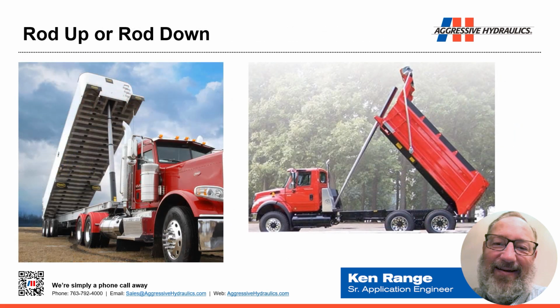You will notice that on some of these dump body arrangements, the case is positioned case down, rod up, or rod down and case up. That typically is a result of the real estate that's available on the vehicle. If you notice on the left, that trailer is basically a flatbed trailer. The cylinder is mounted to the top of that flatbed, and it's simply extending up that dump body.